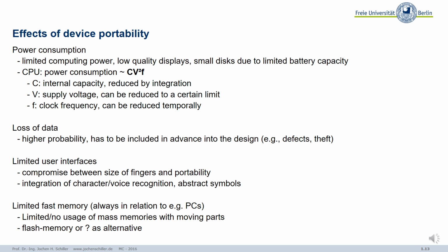So that means if you really want to achieve high performance, you need high parallelism. That means a lot of transistors, higher capacity, and higher frequencies, and that wastes energy. It really wastes it. Why? Well, not in the physical sense, but in the end, it heats up your device. That's exactly, notice, oh, the device becomes warmer and warmer and warmer, so it wastes your battery power. So that's a problem, and still this is the main limiting factor. If you think of smart watches, for example, you have to recharge after 1 day, something like this.